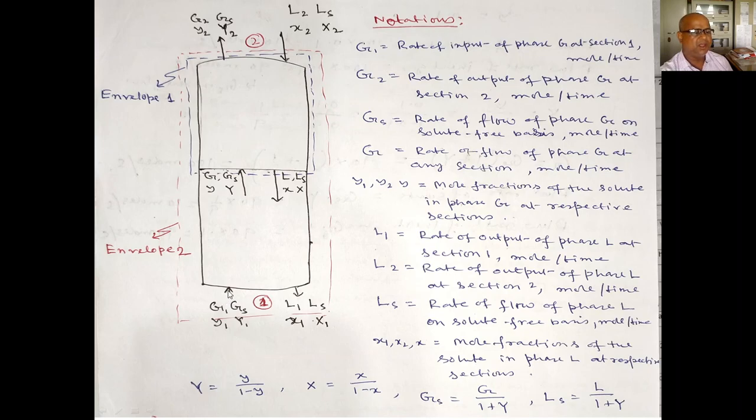That means here it is entering at 100 moles per second. Let's take 2 moles transferred from the gas phase to the liquid phase, so here there will be 98 moles. Here there will be 95 moles. And if y2 equals 0, meaning all ammonia is absorbed, here there will be 90 moles, because 10 moles of ammonia is absorbed between this place and this place. So the G phase total flow rate is changing. You understand what I am telling?